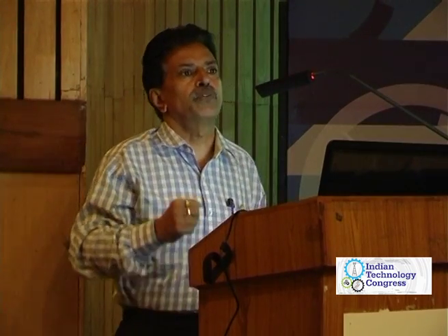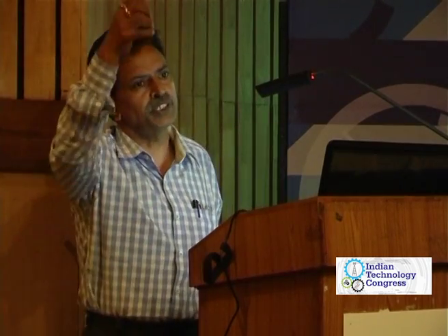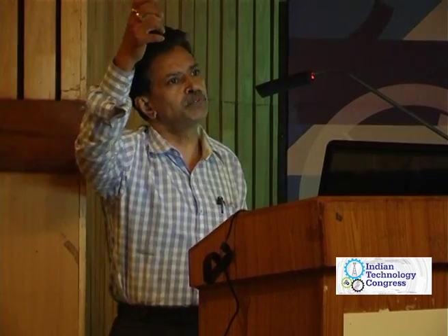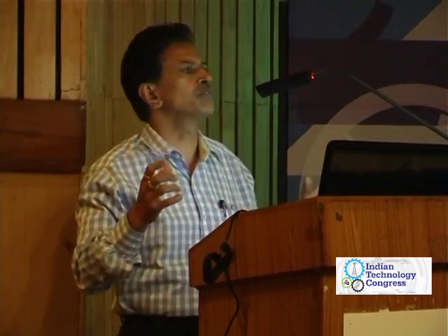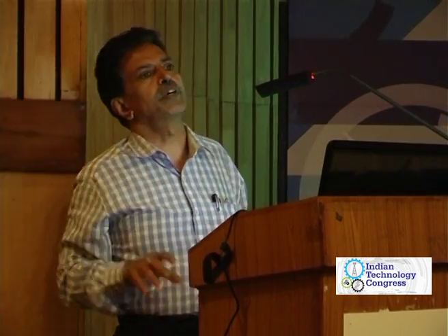So we have in fact tried out with the EVM. In fact, we wanted to make cycle frames. We were successful in making a tube. We had a mandrel. We used our 200-ton press. We got the tubes, and on that we did anodizing. Anodizing again was very difficult. So that's what I will be addressing, the surface treatment of the composites.